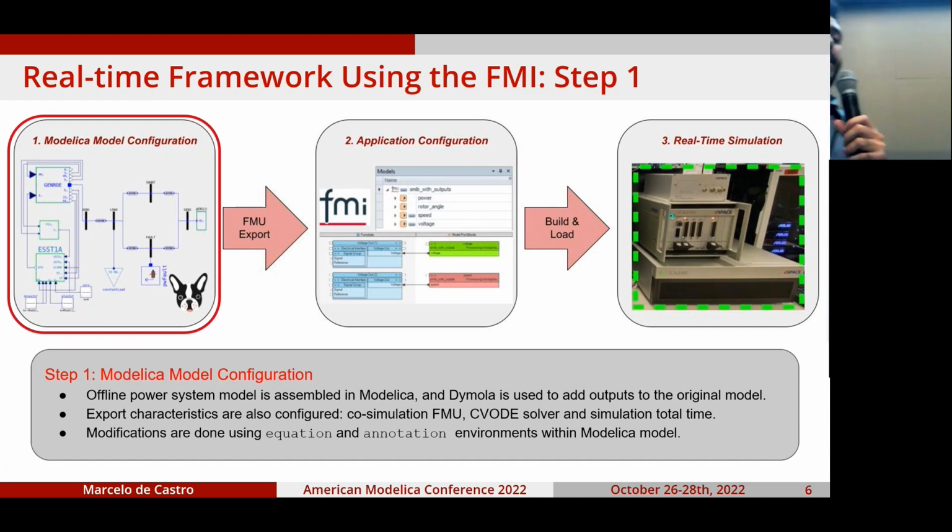And we create the model of a power system here. For those not familiar, this is a phasor representation. So it's an equivalent representation of a power system. And it's perfect for transient stability dynamics, which means that we are thinking about RMS values. So voltage magnitude and voltage angle. We are not looking, for example, in this case, for an EMT simulation in which you're looking at much more detailed operation of devices.